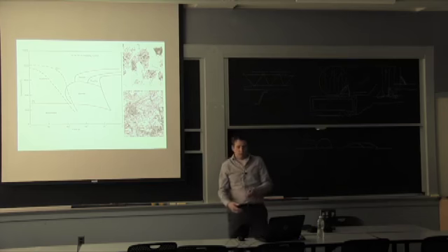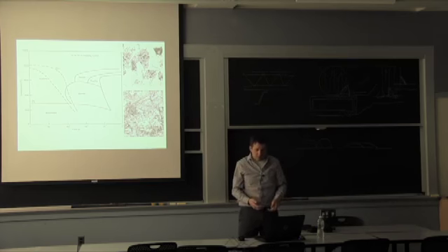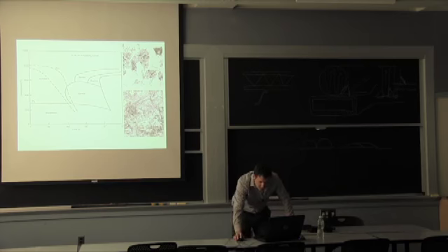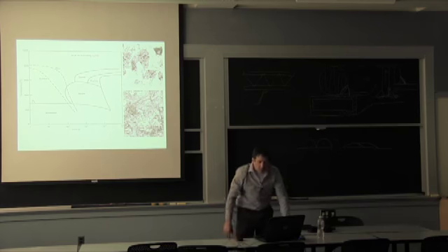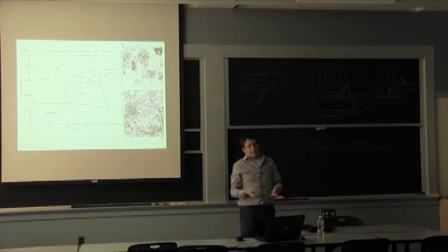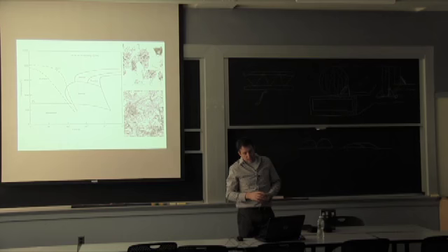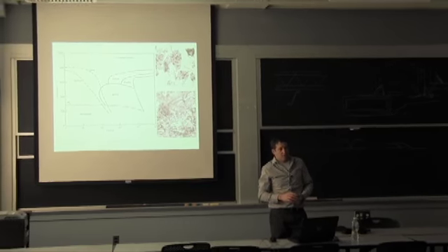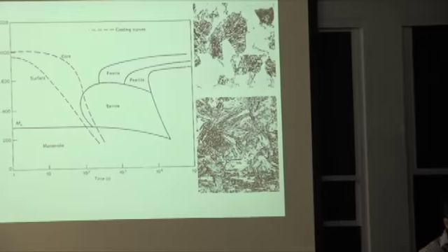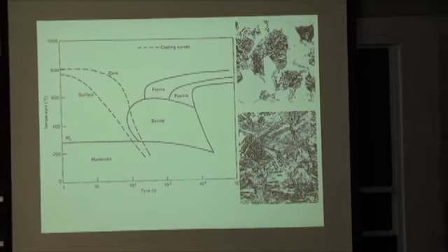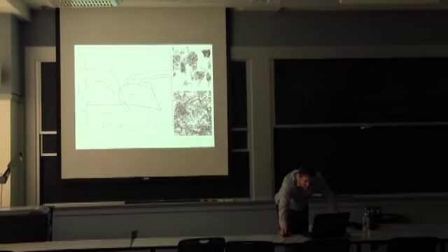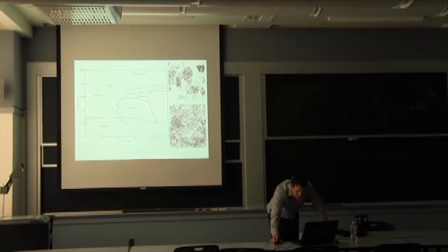Now, strength comes most of the time at the expense of ductility, but this material in general, because you got all these grains, the white grains here are pretty much pure iron, and they're very ductile. So this whole structure is ductile. It doesn't have the maximum strength, but it's something that you can deal with most of the time, and you can weld this structure. What becomes more difficult is when you get this lath type martensite here.